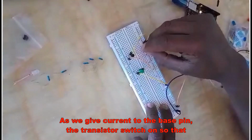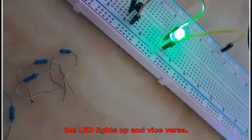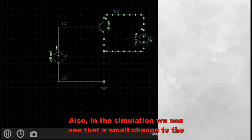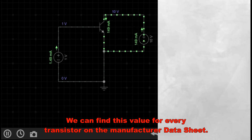As we give current to the base pin, the transistor switches on so that the LED lights up, and vice versa. Also, in the simulation, we can see that a small change to the base current gives rise to a large current on the main circuit. This is called the gain of the transistor. We can find this value for every transistor on the manufacturer datasheet.